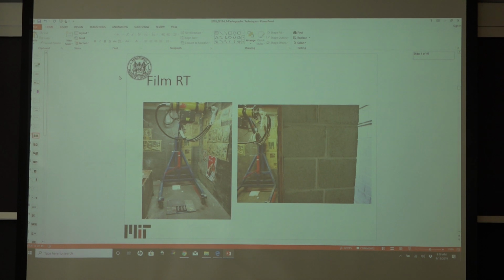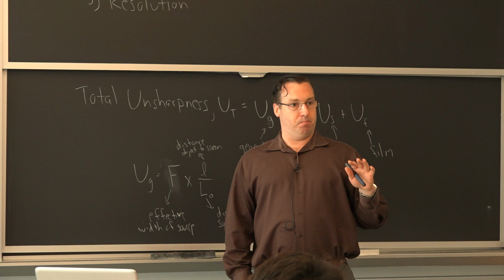So one of the things I discussed before, when you're using radiography and you're looking at large structures, you need to have proper containment so that the X-rays don't come into contact with humans in the vicinity of where the test is occurring. So this is important. This is probably about 1 or 2 meters worth of a concrete bunker. And when they're actually doing the inspection, in the labs they'll have lights going off so people don't come within the area. If you're at a job site or out in the field doing this, they actually have to evacuate the area of other people working.